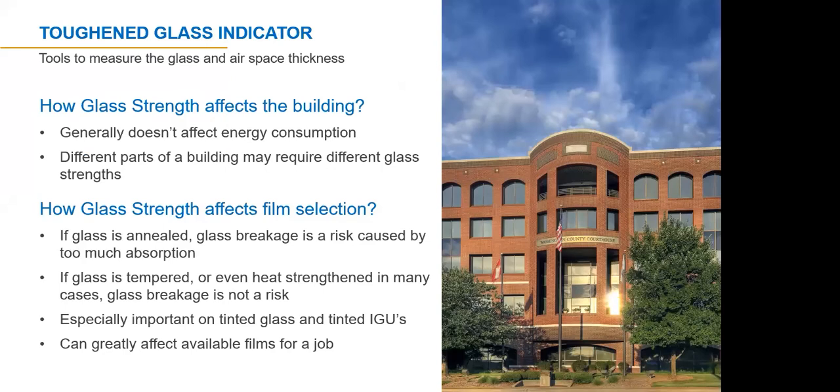The strength of the glass is greatly increased by heat treatment. Heat treating is a process of heating the annealed glass to its softening point and then rapidly cooling it. The rapid cooling cools the surface faster than the interior, locking the glass into a constant state of compression and tension. Tempered glass is safety glass, while heat strengthened is not. Both can receive any type of film without the risk of thermal fractures.